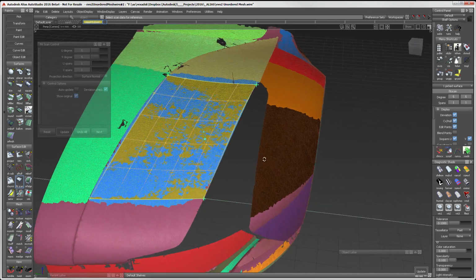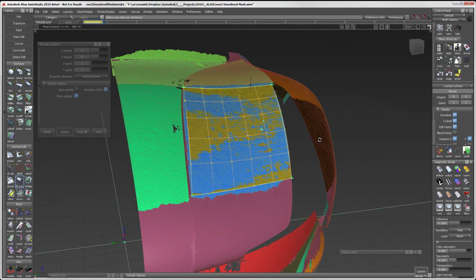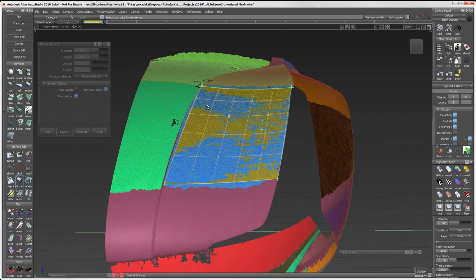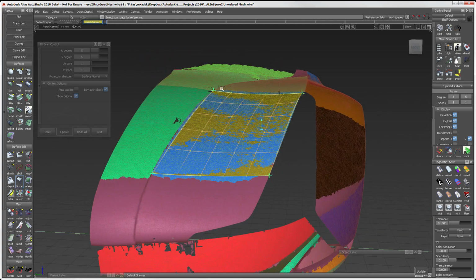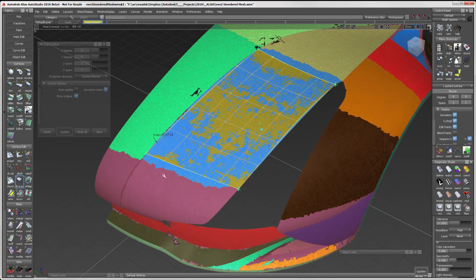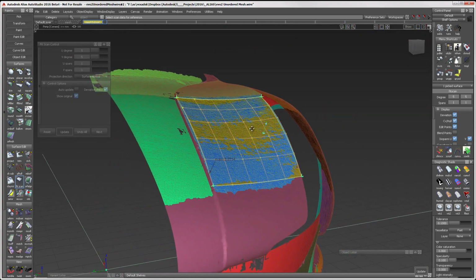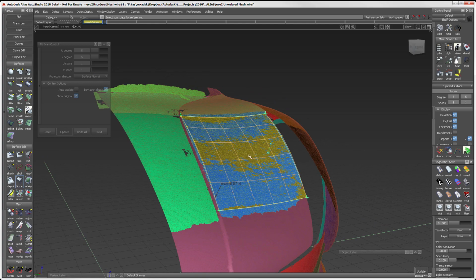When creating surfaces from scan, use random colors and look for a marbling effect showing the surface and the scan are very tight to each other. This surface now has history and can be modified within the session or later by using the Query Edit tool. At the start of the creation mode, I turn Deviation Check on. This feature allows me to see the deviation between the surface and the mesh.